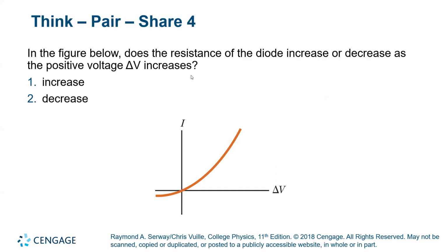So here's a diode diagram. A diode is an element. You have light-emitting diodes, which we're very familiar with, but they don't have to emit light. It's an element that takes a certain amount of energy to allow current to start to flow. And once it starts flowing, it doesn't require any more energy. So the resistance drops, basically almost to 0, as you push through the threshold voltage. As you give it that threshold voltage, suddenly the resistance drops, so it becomes like a conductor.